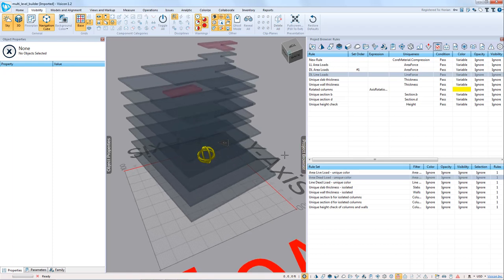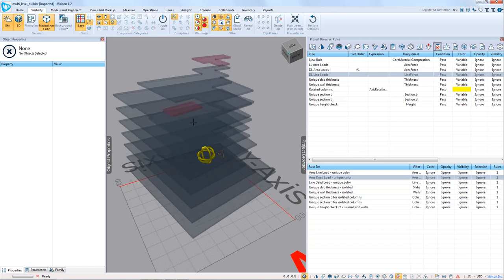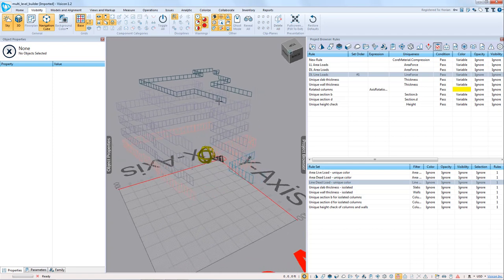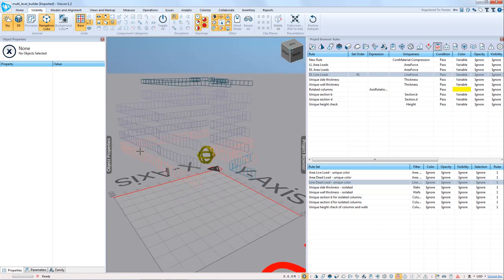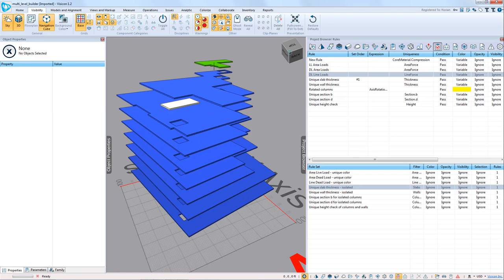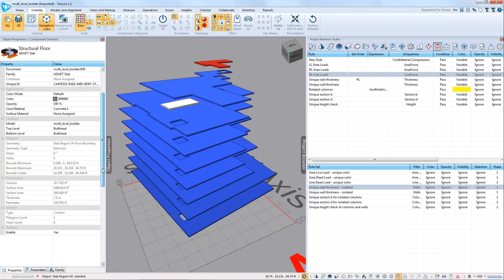We're going to do the same check for our area dead loads. So here I can see that, where I have uniform patches. We can do this for our line loads. So again, I can verify, should I have different line load here where it's pink versus blue? We can isolate various slab thicknesses. So here I can see that this is a green load right there, and this is 7.5 inches. This is a 7-inch slab, and all of the blue ones are uniformly 8 inches.